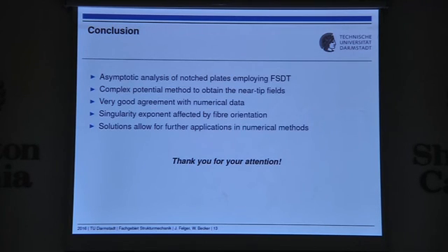And now this nearly closed form analytical solution for the near-tip field can be used in numerical applications, and especially here for very efficient calculations of the stress intensity factors where you have to know the asymptotic near-tip field.